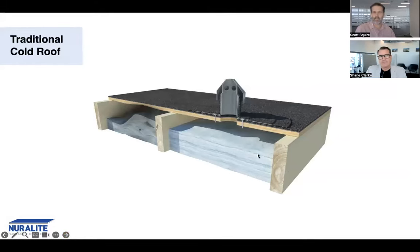Now, E2/AS1 requires the framing at 400 mil centres. Our 3PM system, it's CodeMark certified, which requires framing at 600 mil centres both ways. The approach that you can see, there's a couple of pitfalls to it, or challenges, I guess, obviously thinking about labour and material costs of that supporting structure. It's quite involved. We know with the new H1 roof insulation requirements, we're seeing much higher levels of insulation required.